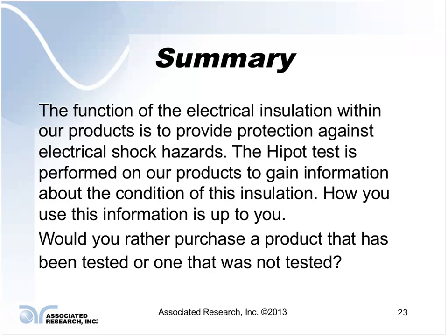So, the product was in fact operating when I took it out of service, and now when I did a repeated Hipot test on it, it failed. But wasn't that the purpose of doing the test itself? Was to determine whether that insulation was good or bad? So again, keep in mind, why are you doing the test? You're actually testing the insulation to make sure that you do not have any of these hazards that could exist, that could create a potential shock or fire hazard.